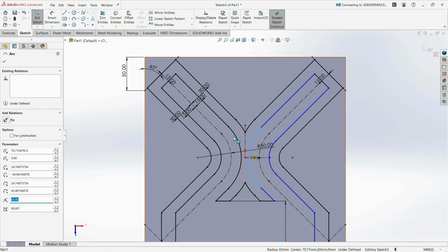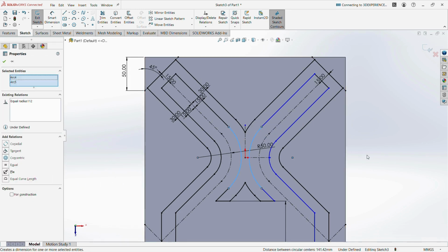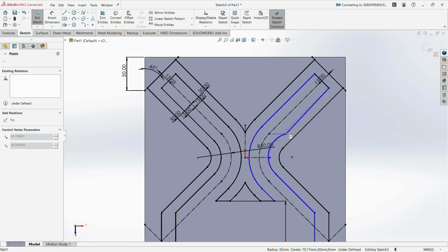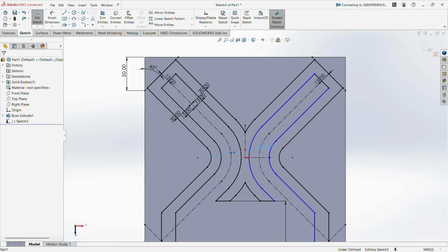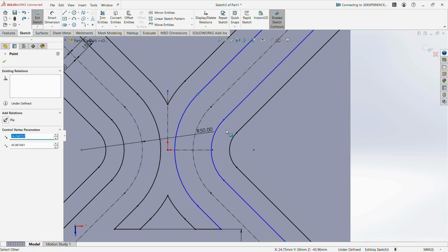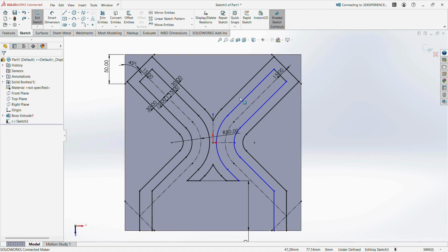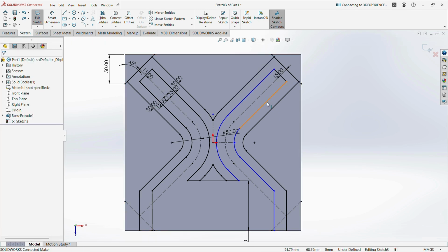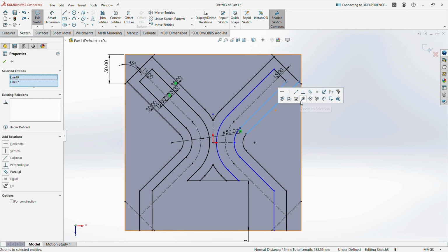Once it is trimmed, now choose this particular portion, initiating an equal radius by selecting its opposite profile. This point is not constrained equally. So now select each of its points and fix it tangentially, because we deleted these offset entities, and initiate new kinds of geometrical constraints on this particular profile. Both the geometrical constraints as well as the dimensional constraints on this particular area. So now select the two opposite lines, mention the parallel constraint. Same as the opposite one, mention the parallel constraint.